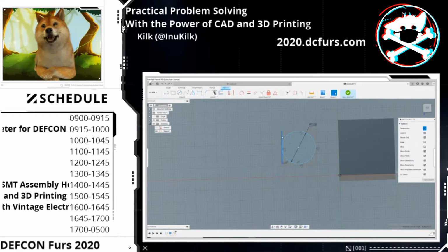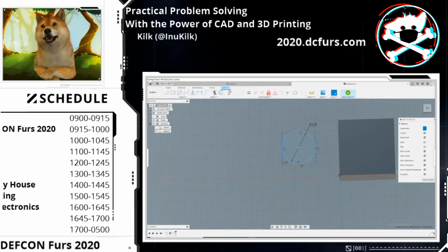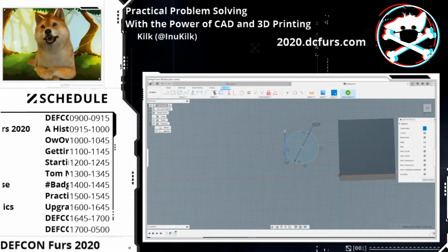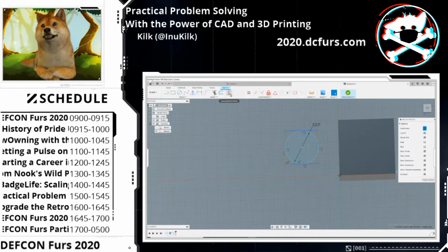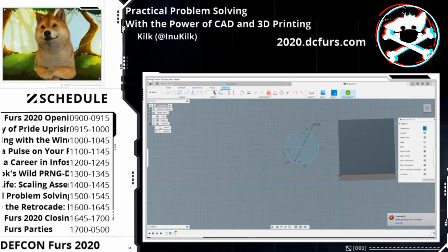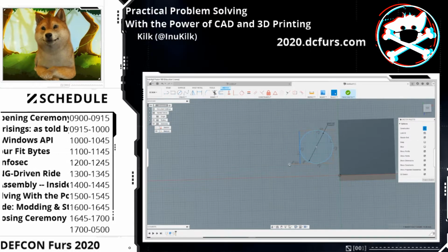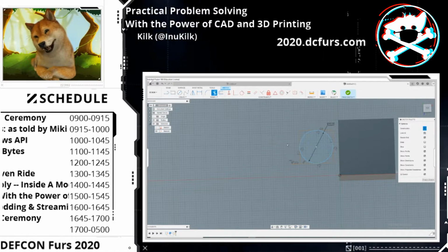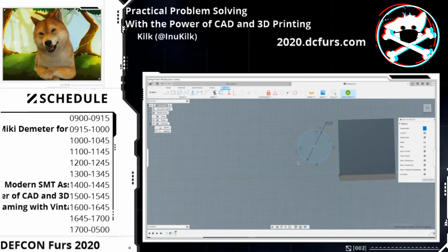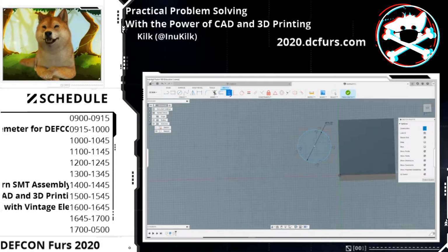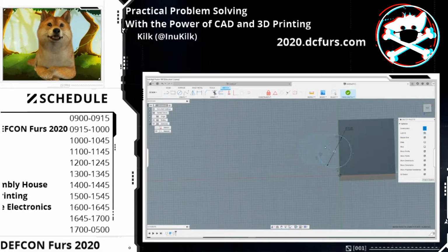Oh, that's right. What you need to do is make sure that these are also vertical. So now they can't move at all. And these need to have the horizontal constraint. So now it'll be perfect, except there's a problem here. This is not coincident. We're going to just trim that. So now it's perfect, except... there we go. It should stay there and should move like that.